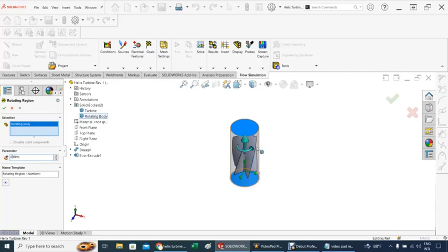As you allow the blade to spin, now you're extracting energy, but the torque will get to a smaller value, and a smaller value. There is a value where the torque is actually zero, that there's no torque required, and you will say that the spinner is what is called free spinning.